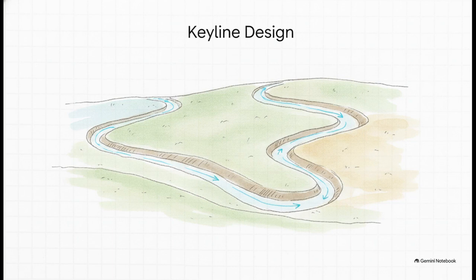So to fix this uneven flow, we look to keyline design, formulated by P.A. Yeomans. We use contour line swales, which are basically shallow, level trenches to spread and sink that water. By creating off-contour rip lines that loop higher in the valleys and lower on the ridges, we actively reverse the whole concentration pattern. We capture runoff at high elevations and direct it laterally toward those dry ridges.